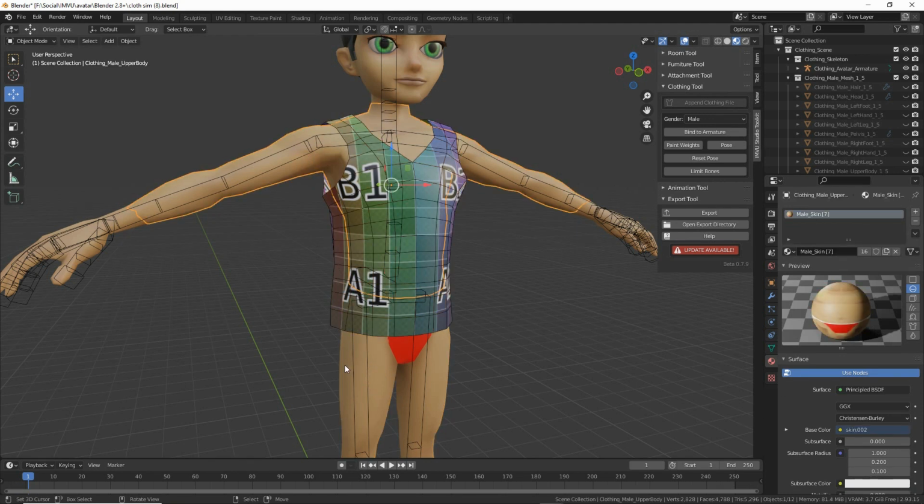But because of the way that this works, what we want to do is do all the body parts at the same time. Otherwise, when we copy the weights for one section, and then try to copy the weights for the other section, this will override the original weights.